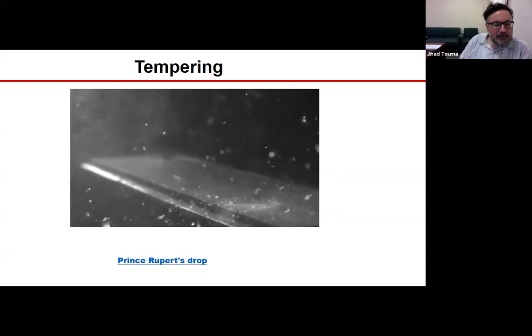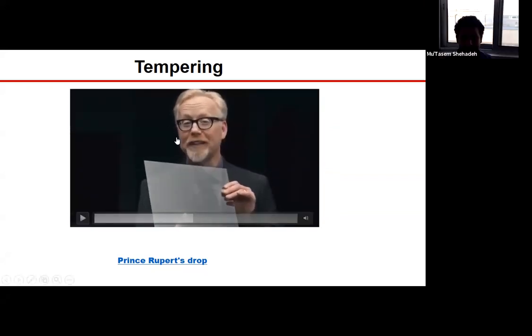Yes, I was referring to this stress release as part of the experiment. So if you're talking about the solidification process itself, where you have a molten glass that is cooled very rapidly, the outer surface will be in compression compared to the core that will be in tension. You know, one can use, in my opinion, CFD, computational fluid dynamics, to simulate this behavior.